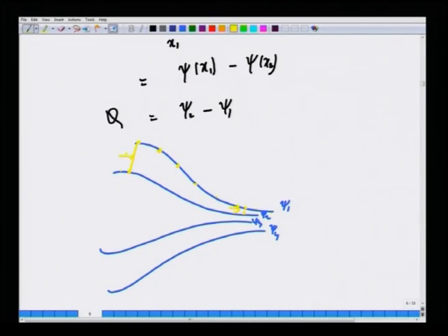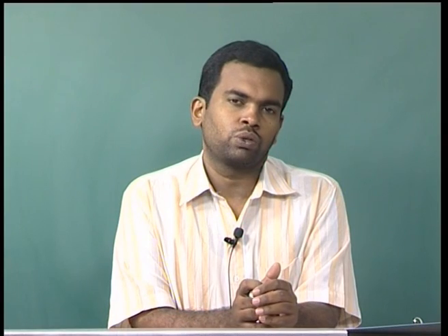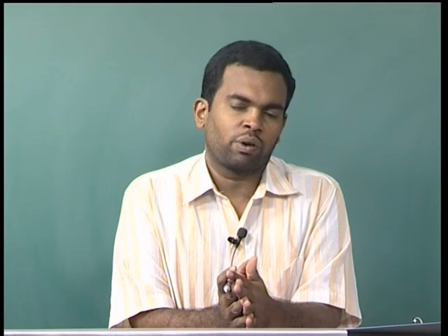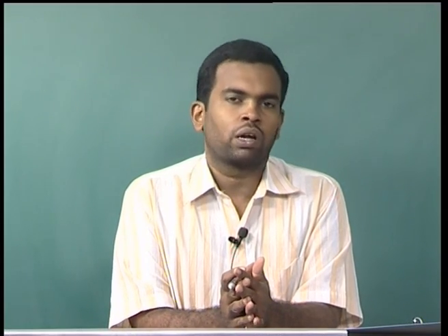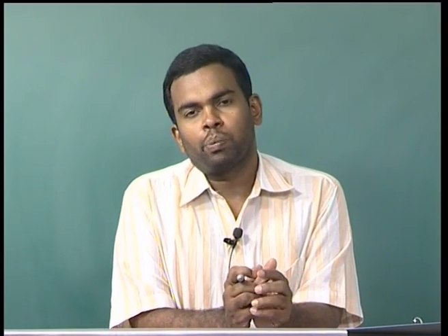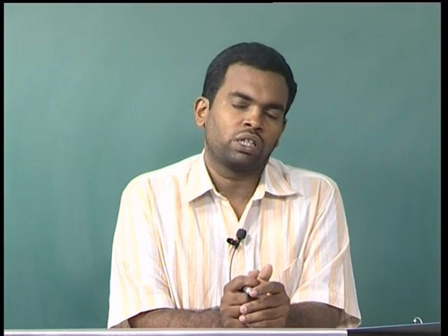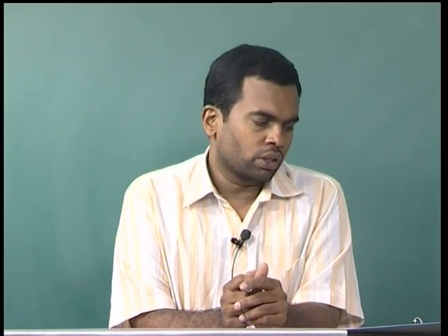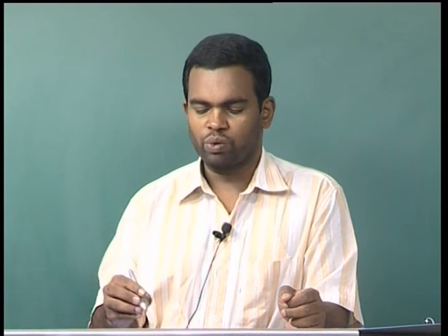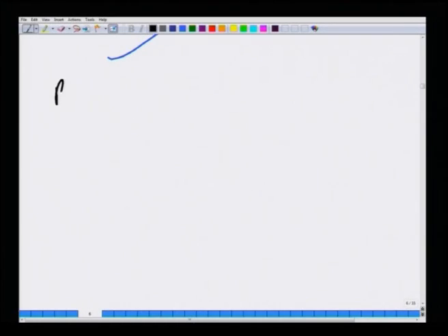So, this gives rise to a very quick aid for flow visualization, because once you have a huge amount of data, let us say from a computer solution or an experiment, by plotting all the data in terms of streamlines, one can immediately get a qualitative feel as to where the flow velocities are large and where they are small. Okay. So, this is the big advantage of the differential stream function. So, just to recapitulate what we did in today's lecture.